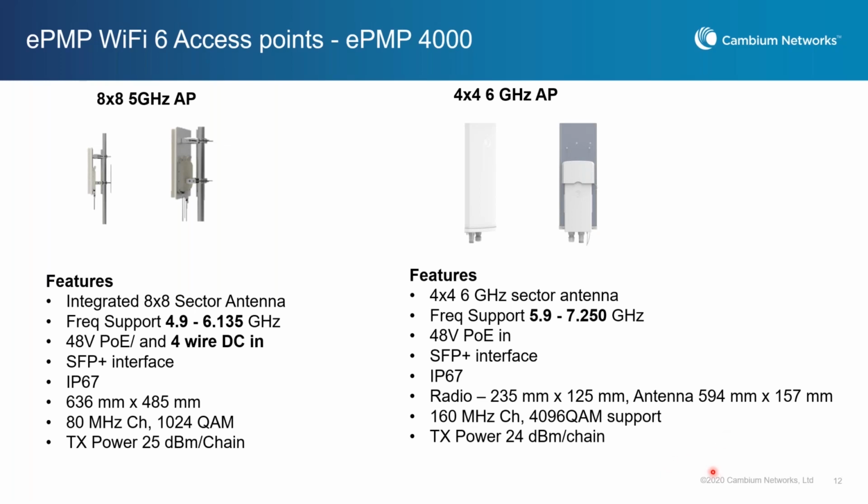While you're looking for the question, regarding the distance on the Force 425, I would encourage everybody to go to the link planner, because it can give you a rough idea. You can play with different antenna sizes, and you can see when you will get high order modulations. The rule of thumb: if you are in the higher 30s in terms of the signal-to-noise ratio, you will probably get the highest modulation if there is no interference.